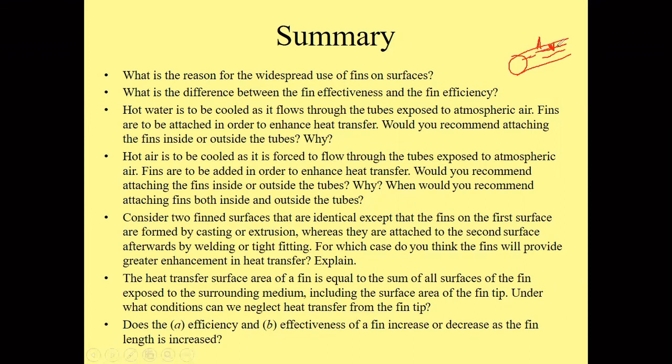There should be a higher heat transfer coefficient inside, and then you enhance the lower one, that is at the outside part. Okay, so that's why it's better to put it outside the tube.